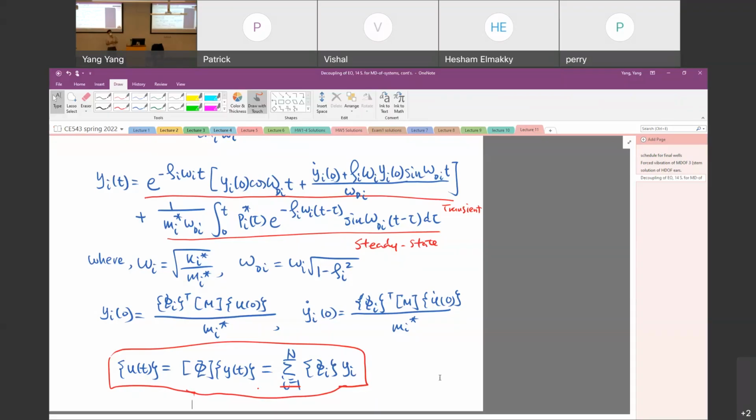That's what you need to do for your project. If you follow this procedure, you should be in good shape for your project. You figure out the mass matrix, the stiffness matrix, and you assume a damping matrix here, so that you can solve the system under earthquake using numerical methods.